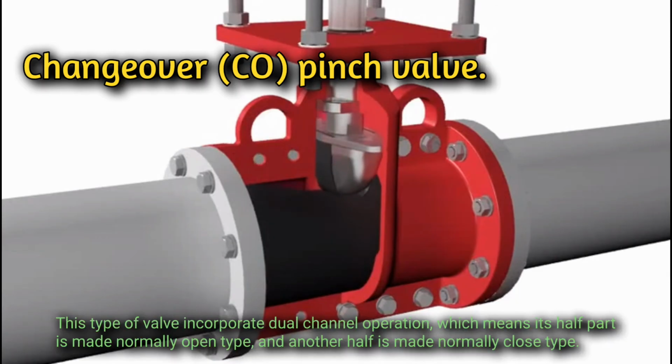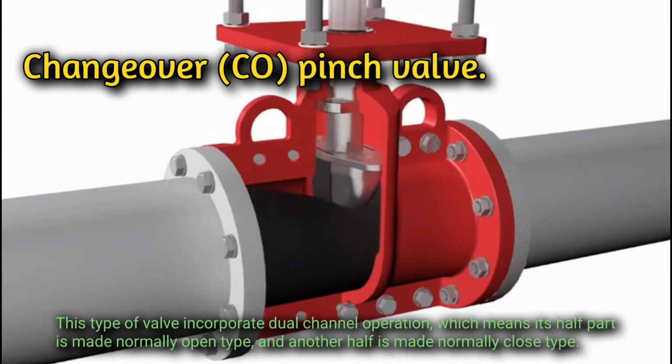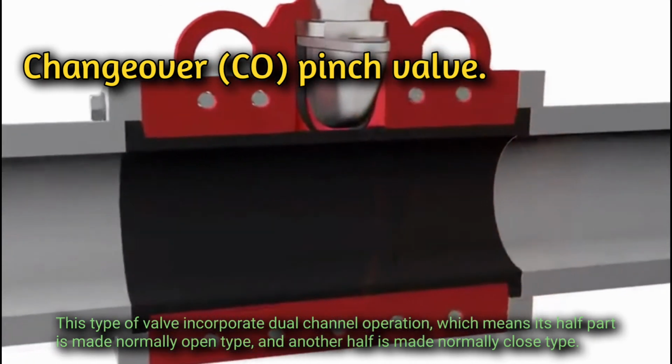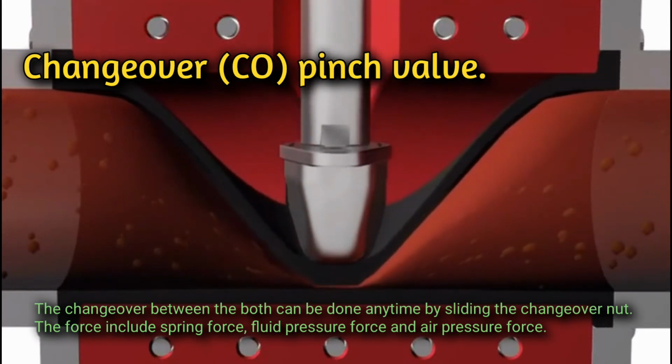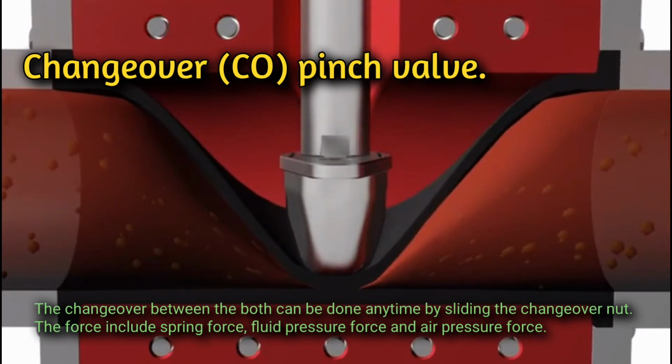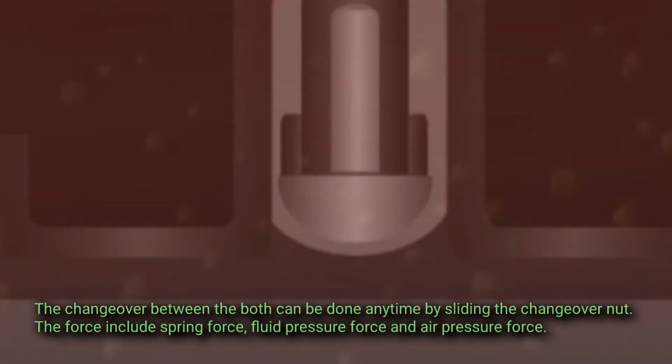Changeover pinch valve. This type of valve incorporates dual channel operation, which means half of it is made normally open type, and the other half is made normally closed type. The changeover between the two can be done anytime by sliding the changeover nut. The force includes spring force, fluid pressure force and air pressure force.